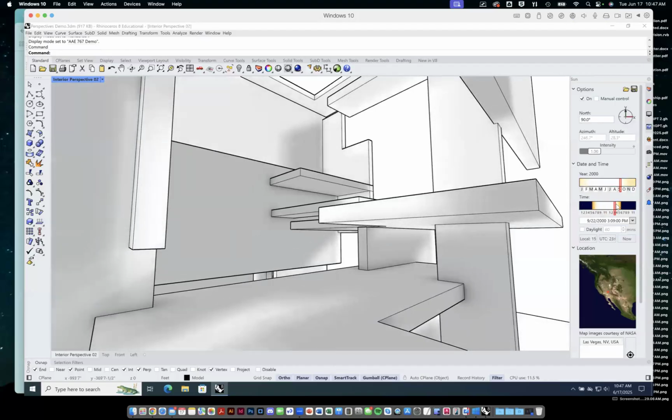And what I might start to see is that in the afternoon, I have way too much light in here, and I need to start actually adding cladding to the outside, right? In other words, light isn't that special unless there's some dark to contrast with, right? There's shadow, right? So trying to understand that can be, I think, really helpful. And light can be great if you can bounce it in and diffuse it before it comes into the building. But if it's direct sunlight, again, we get that direct sunlight hitting the surfaces on the inside of the building.